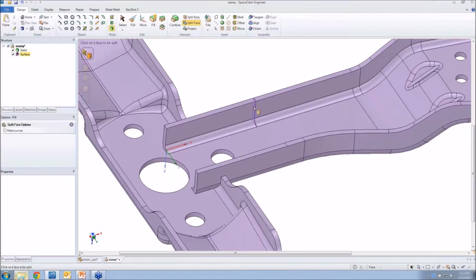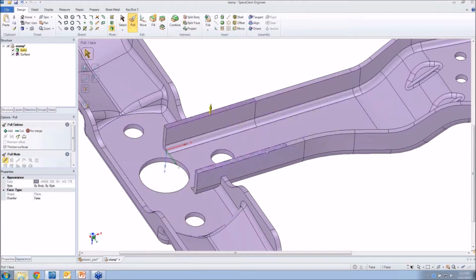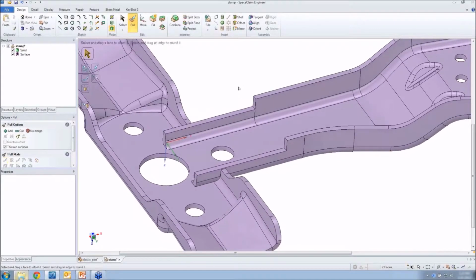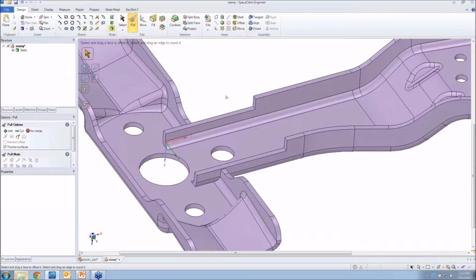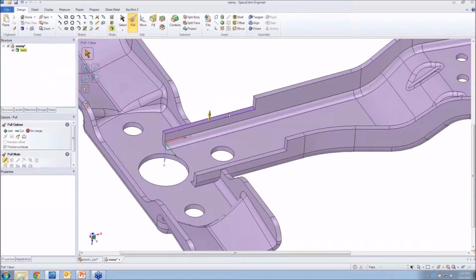I'm taking a couple of faces and cutting them, making a division, and that reference face did it all for me, all with the pull tool. It's all I had to do. That reference face sitting there, I could delete that now without repercussion. This is something that just speeds you up big time in this software. You don't have to worry about messing up relationships in a model.